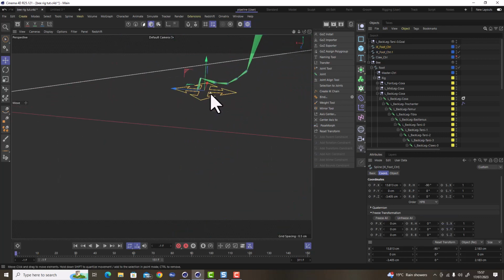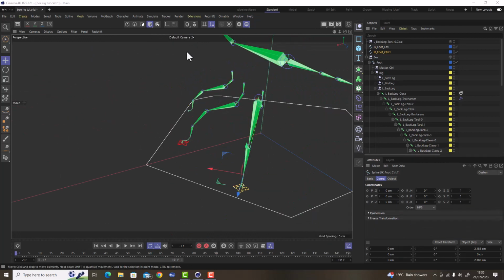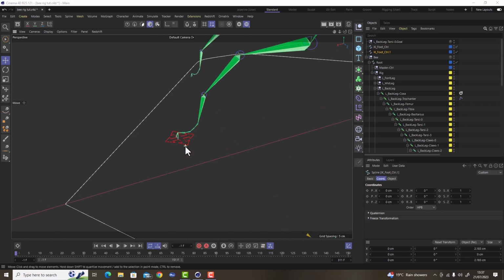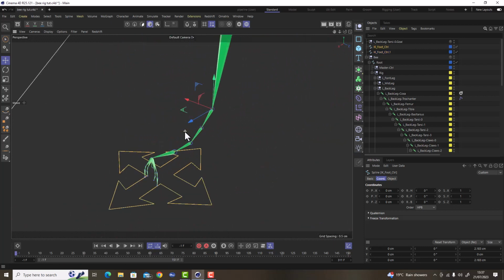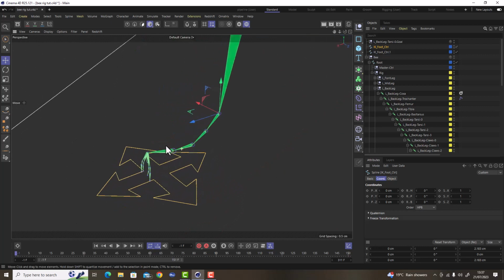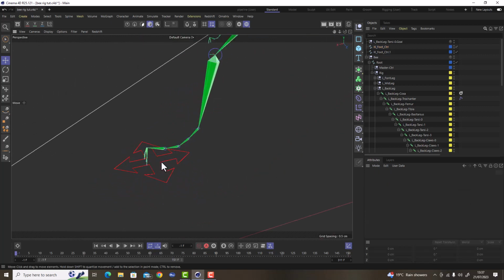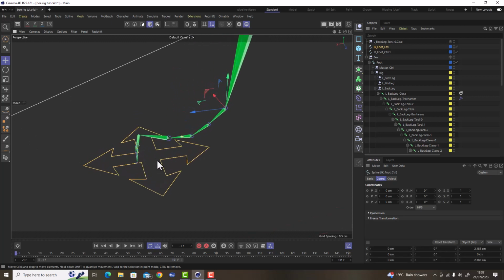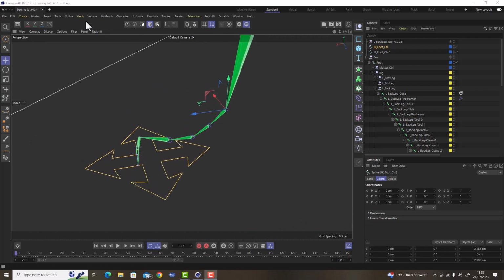It's so important. The only other thing we have to do before we move on to the next stage is just to make sure that the controller in which we copied it from is aligned with its pivot point in the right place. I went ahead and done this. This is by using exactly the same technique so far, and that is that if your pivot point of your controller is in the wrong place, we just simply activate our axis tool, enable snapping, and then just move it over until it's snapped to that joint. You can use the transfer tool, but sometimes the axis snapping is fine.